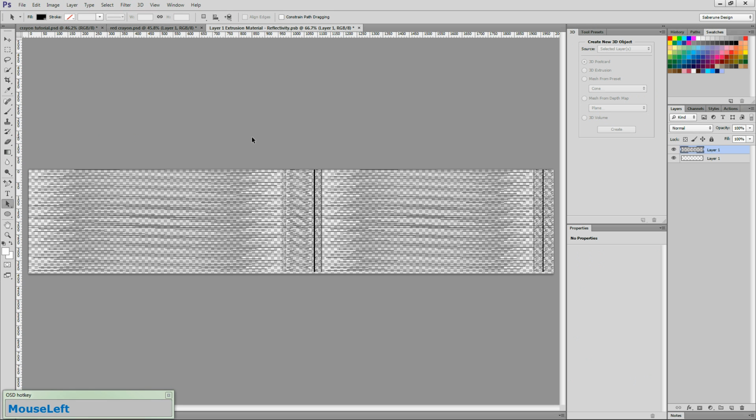The caveat to the whole thing is we're using the same diffuse color to color both our label and the shiny wax that the crayon is made out of. So we can't just adjust the numbers. If we do, the wax won't be shiny anymore. So we're going to use a map to sort of shield parts of the mesh from our overall settings. As I said earlier, it works on the exact same principle as using an alpha channel to manipulate transparency.